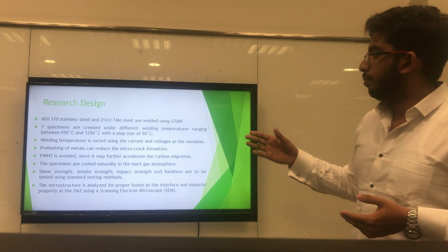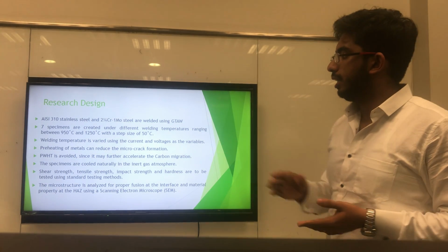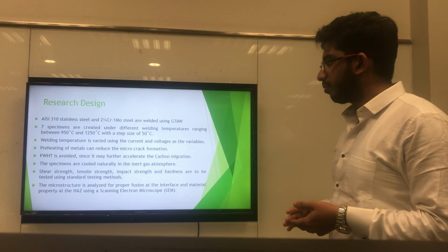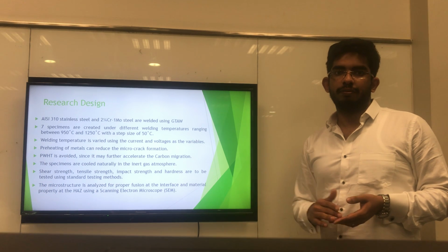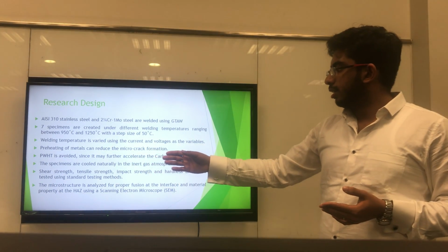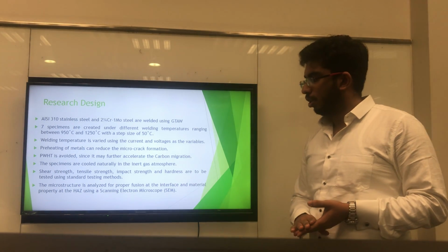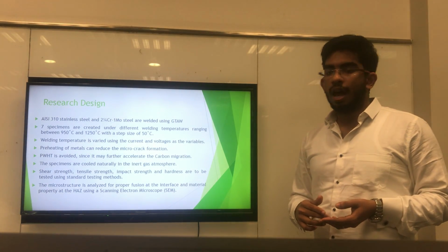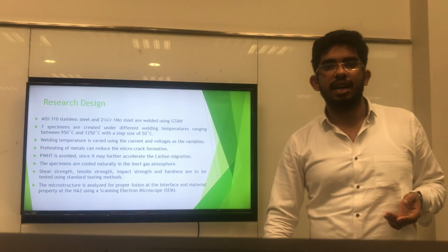The preheating of the metals can reduce the microcracks, whereas post-weld heat treatment is to be avoided since it may assist the carbon migration. The specimen is cooled naturally so as to prevent the microcracks again. And it is subjected to mechanical testing such as shear strength test, tensile strength test, impact test, and hardness test using the standard methods. Finally, the microstructures are analyzed for proper fusion as well as the mechanical properties of the heat affected zones using a scanning electron microscope.